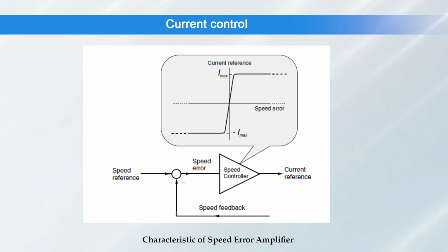In other words, we can expect the actual motor current to follow the current reference signal at all times, the armature voltage being automatically adjusted by the controller, so that regardless of the speed of the motor, the current has the correct value. Of course, no control system can be perfect, but it is usual for the current error amplifier to be of proportional plus integral, or PI, type, in which case the actual and demanded currents will be exactly equal under steady state conditions.